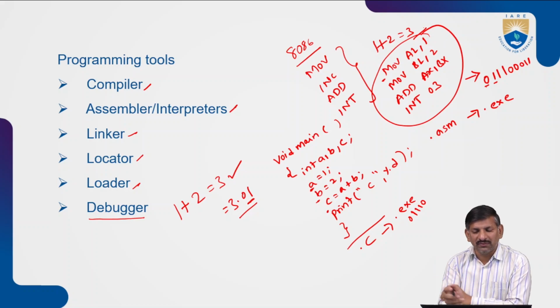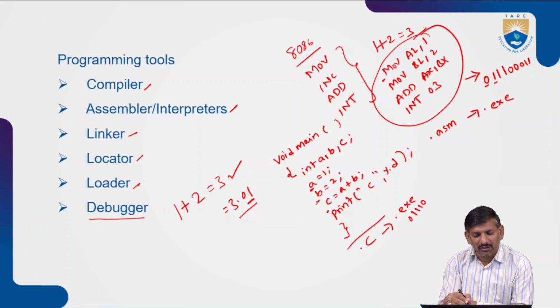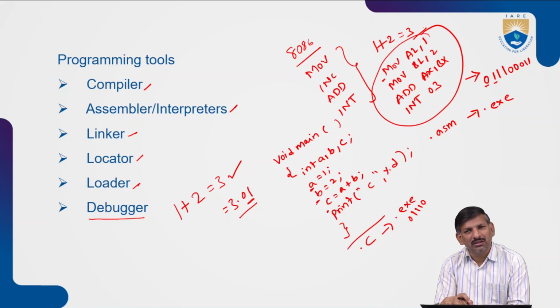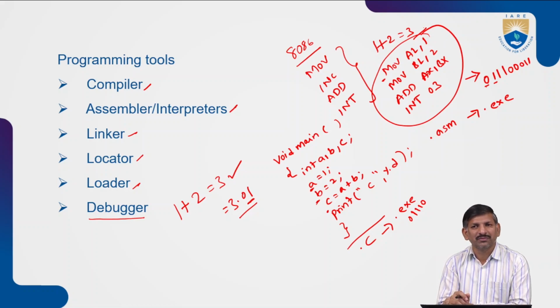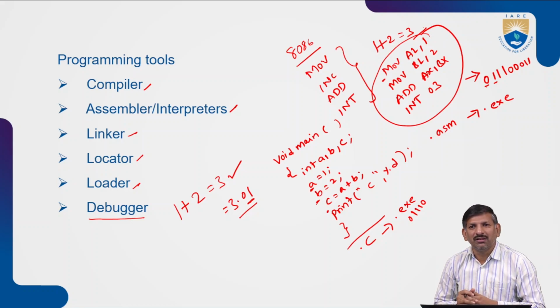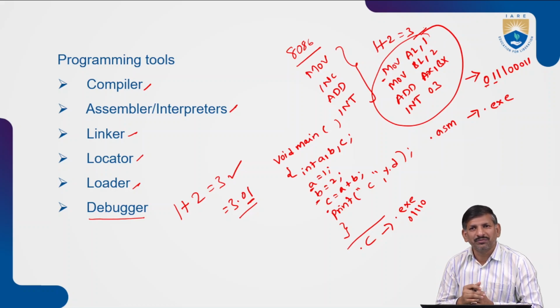At that time, I check the value of A. At the next breakpoint, after pressing run again, I get the B value. You need to check whether the A value is 1 after executing that, or whether any other value is there. Wherever we want to check the functionality, we can set breakpoints up to there and verify it.